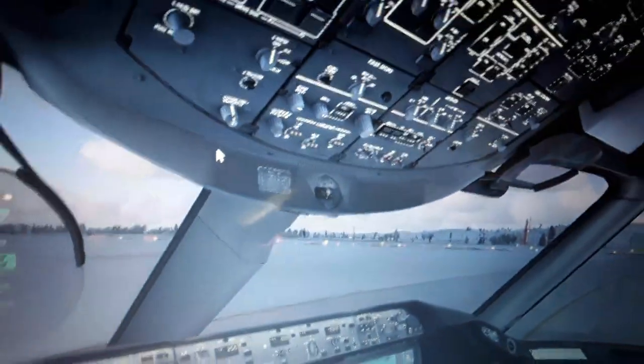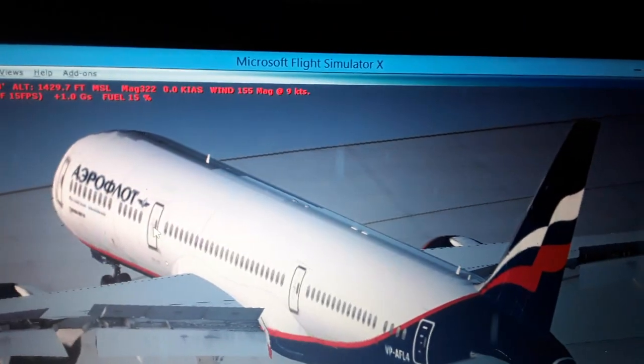So this is a fly-by-wire aircraft. It has its own flight control computers like in the Airbus aircraft. You have the normal, the alternate and the direct control of the flight control computers, the modes of the flight control computers. So if you have failures or you disconnect the flight control computers in the Airbus, you can degrade the flight control modes and the protections you have.